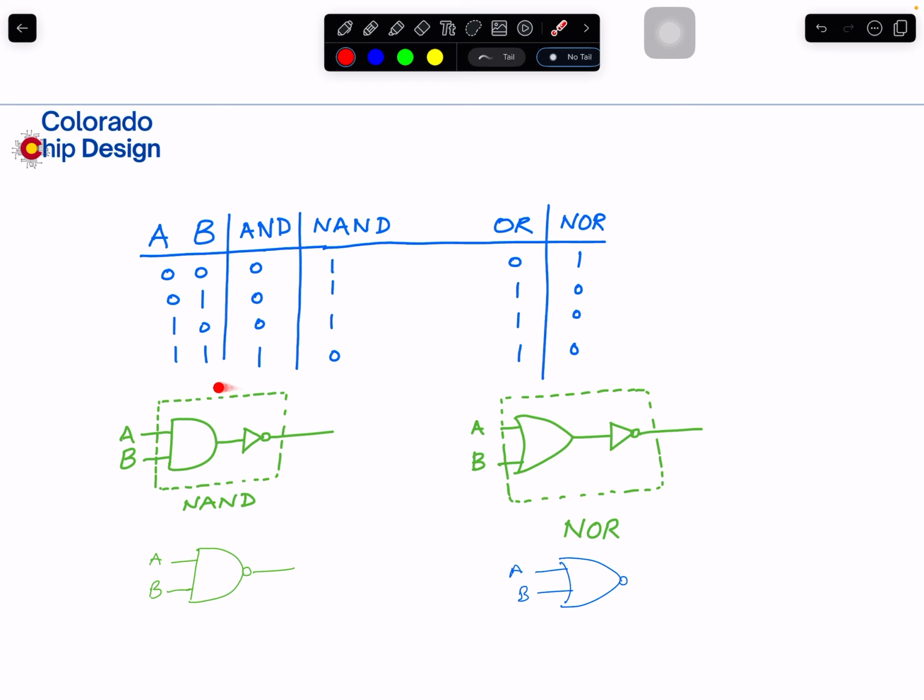So NAND is considered a basic unit in how we sometimes compare two designs. How many gates are in one? So all we do is ask how many NAND gates are in one design compared to another one. What is the NAND area in one technology versus another technology? So that is a good reflection of some of the basics when you compare technologies on design. Okay, so that's NAND.